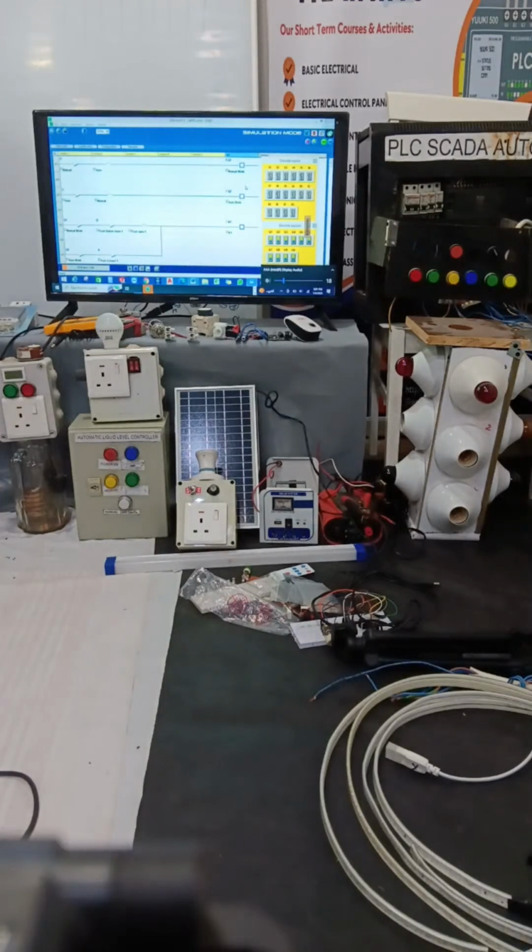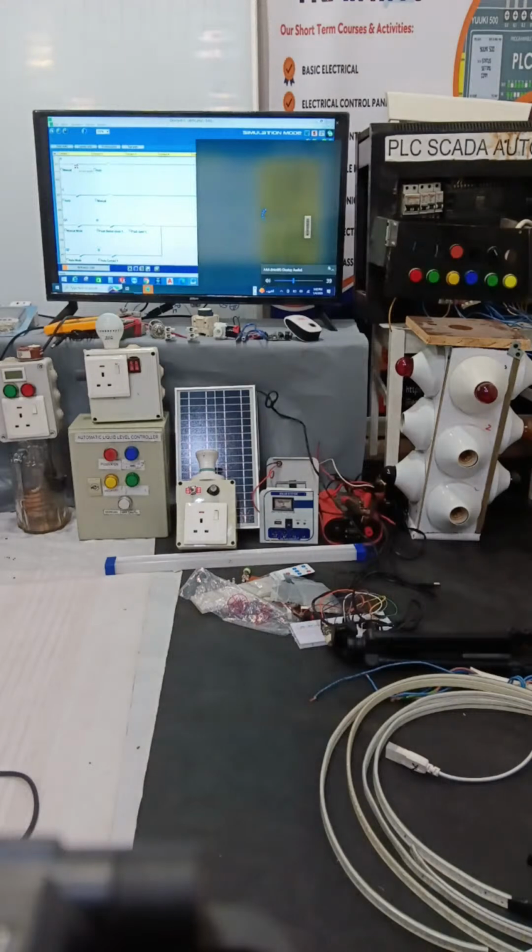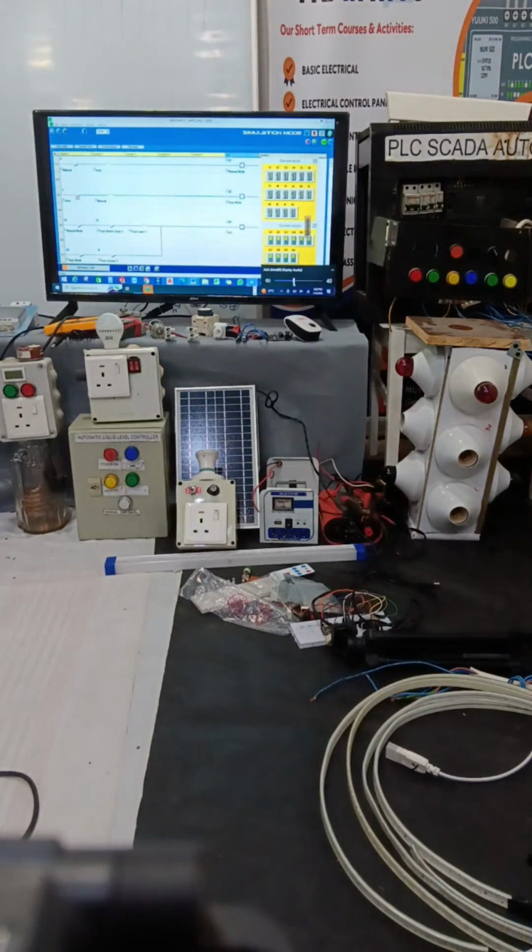So this is the electrical diagram equivalent of the logic. In our electrical diagram, we have one auto manual switch. Here this is the auto, and this is the manual. When we close the manual position, one lamp glows, indicating the manual mode is on. When we turn the switch to auto mode, this lamp indicates auto mode.